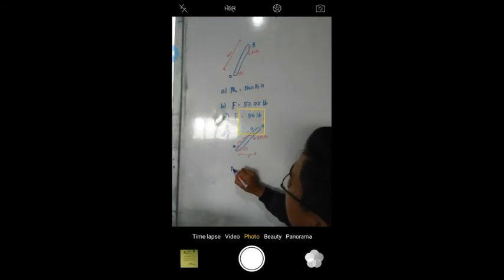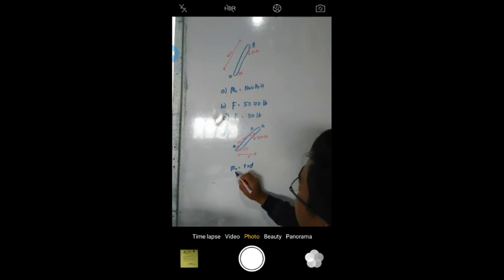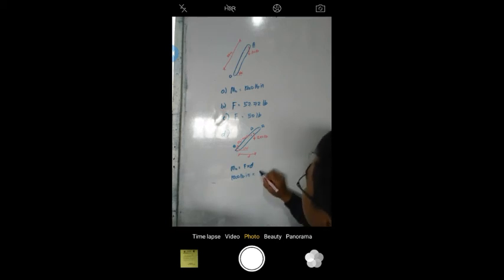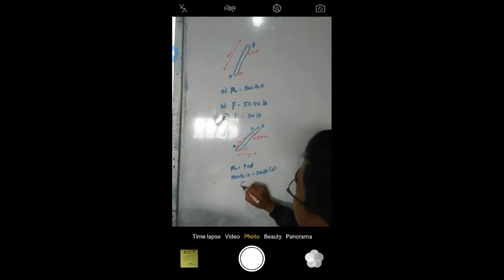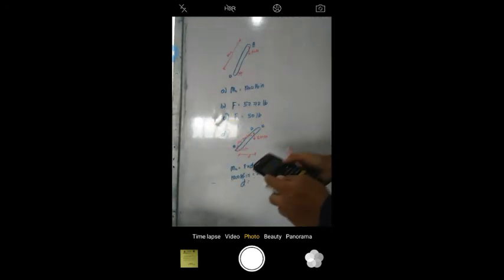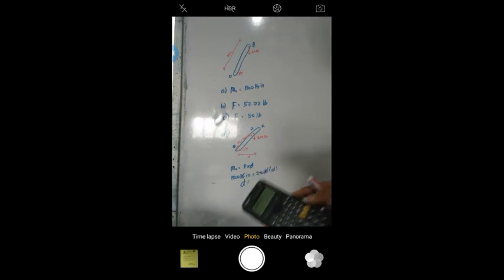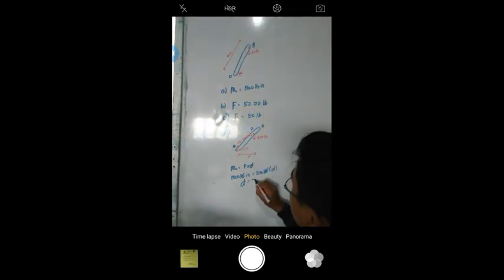As you can see, moment at O is equal to force times distance. So our moment, 1,200 pounds-inch, equals the force, which is 240 pounds, times the distance. The pounds cancel, and only inches remain. So 1,200 divided by 240, and the distance here is 5 inches.